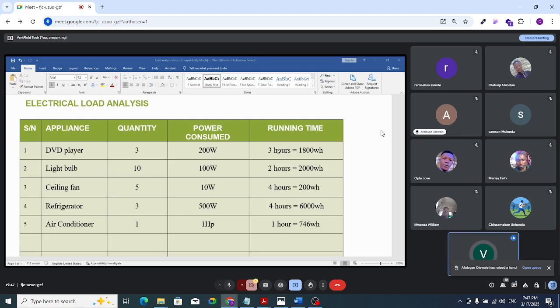The nameplate is that place, position, or portion on the body of the appliance or packaging, which is the carton of the appliance, which states out clearly all the parameters, all the information regarding that appliance. It tells you about the maker of the appliance, country of make, voltage, rated current, rated wattage. So you just go there, lift your rated wattage, and then you are good to go. In watt: 100 watt, 200 watt, 300 watt, 400 watt, 500 watt.